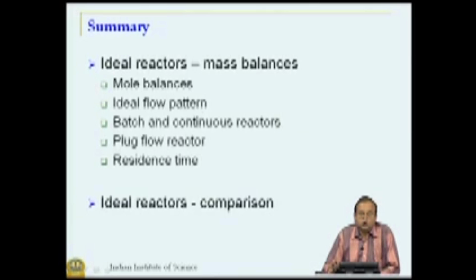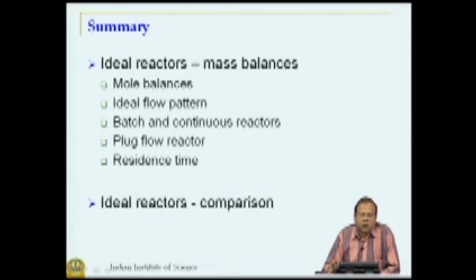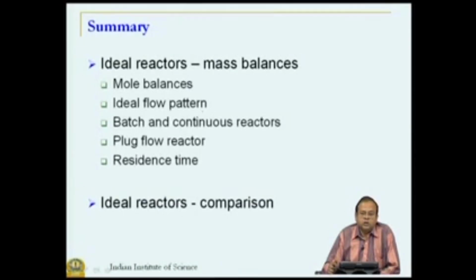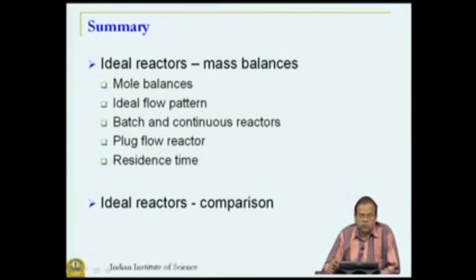Towards the end, we also looked at how we can compare the performance of two reactors, namely stirred tank reactor and plug flow reactor, and came to the conclusion that for reactions which follow power law kinetics with power being a positive number, plug flow reactor will always give you better conversions than the same volume operated in a stirred reactor manner. But there are situations where stirred reactor will give you better conversions, both isothermal as well as non-isothermal.